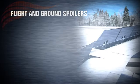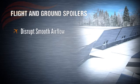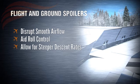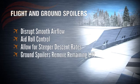Flight spoilers are panels on the upper surface of each wing that disrupt smooth airflow. As we discussed before during this lesson, they're used in flight for two purposes: to aid roll control and to allow for steeper rates of descent without a significant increase in airspeed. Ground spoilers are used on ground to destroy all excess lift when the aircraft lands, so that the wheels have better adherence to the runway and braking action is improved. In other words, the weight is shifted from the wings to the wheels.